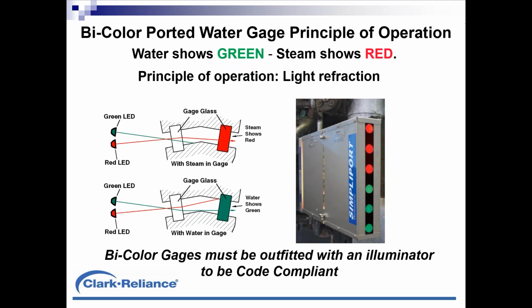And one way to test that is to isolate the gauge, repair one port, both sides, return the gauge to service. You'll see a nice vivid green again, as well as the evidence on the parts you remove that would indicate to you that it's time to rebuild the rest of the gauge.